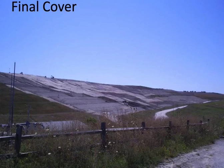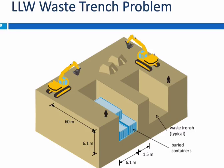And also for everyone's reference, the view of a final cover system in various stages of construction. In this case, we can see the geomembrane layer is exposed and has not yet been covered by the protective soil or the vegetative topsoil. Again, a useful reference for the technology that's being used here. Same technology for a final cover system for municipal solid waste landfills, of which we have lots of design experience, is very similar to what is being used for low-level radioactive waste landfills.